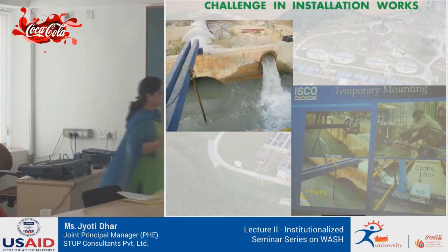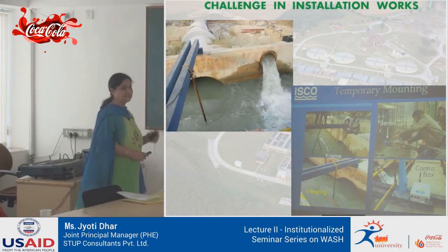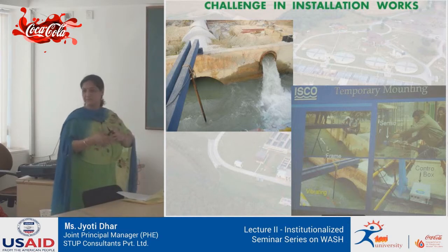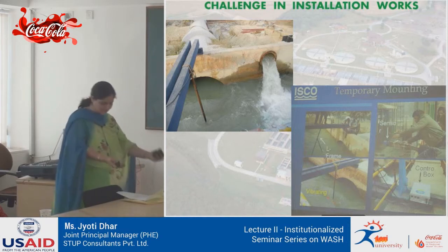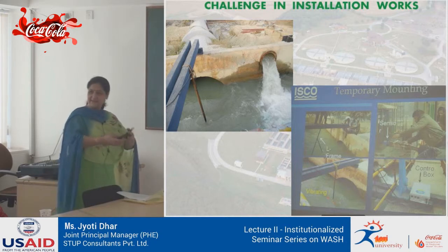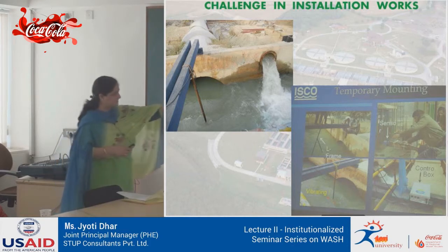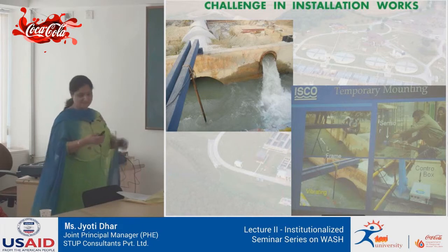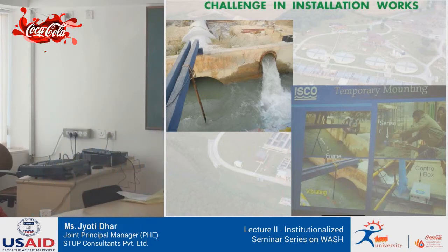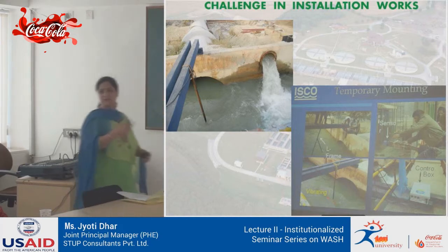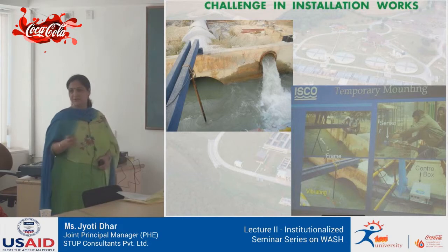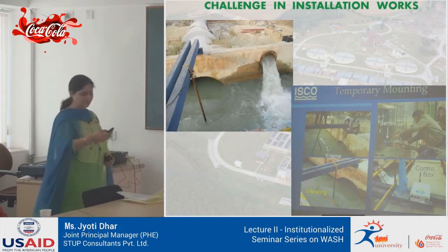So what we did, you can see a person standing there on the wall. Though it was very tough, he tried to install the system there. It was a Teledyne system which is based on the Doppler principle. It's an ultrasonic sensor which is installed at the bottom of the pipe, and you get the flow data from that based on the Doppler, ultrasonic principle. You can see the person installing the sensor just on the pipeline, and we had installed a frame here and the sensor was dipped into the water. This is flowing water. You need not shut down anything. It was just inline, you have to install.